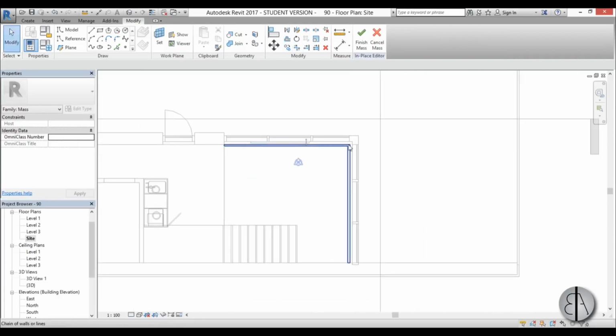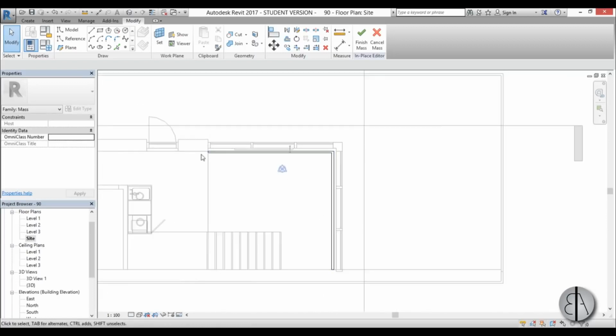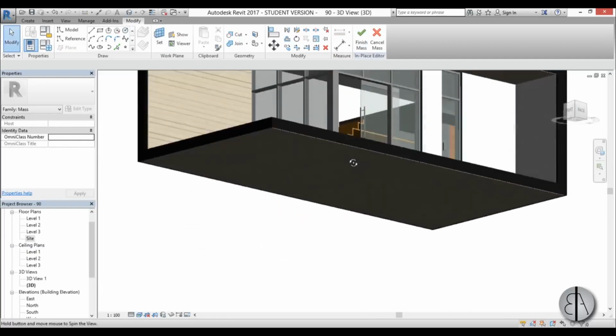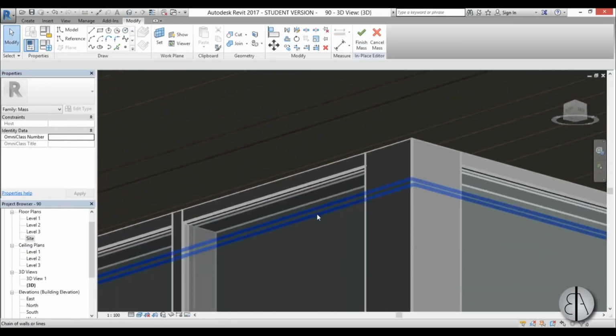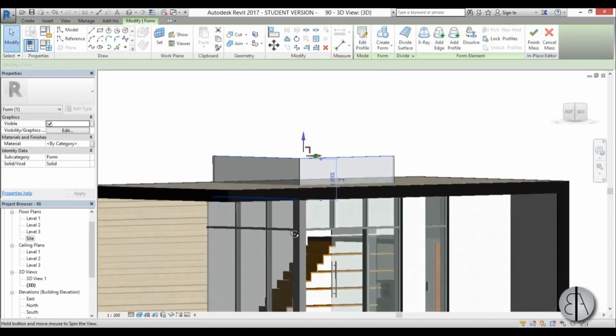So you kinda create this L-shaped or reverse upside down L shape element, and this will be your curtain railing, or the thing that actually holds the curtains on the ceiling. So you just go finish, or not finish, you just go into 3D like so. You kind of find that, and you go here, create form, and it creates a sort of an extrusion.